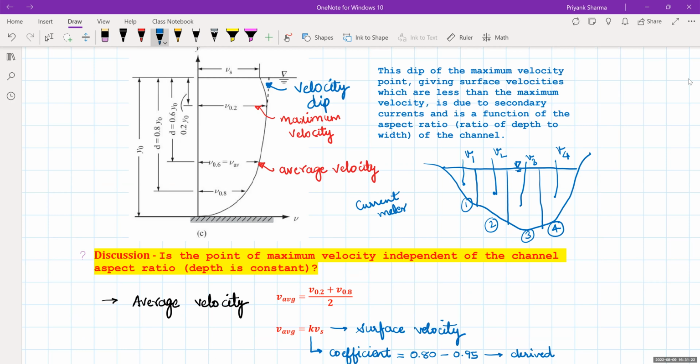So I multiply the velocity with the area, and then I'll get the discharge, or you can take V1 Y1 and then multiply by the width also. Similarly, you get the total Q as the summation of Vi Yi Bi. So this is your total discharge which is passing through each cross section, and then it is summed up. So that will give you your total discharge passing through a section, and that is why it is very important at which point you measure the average velocity.